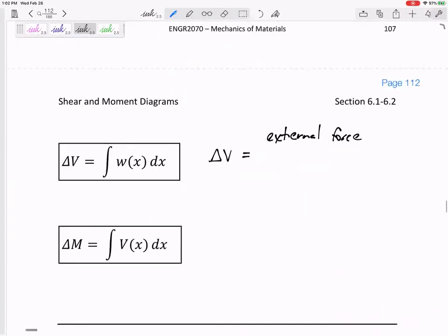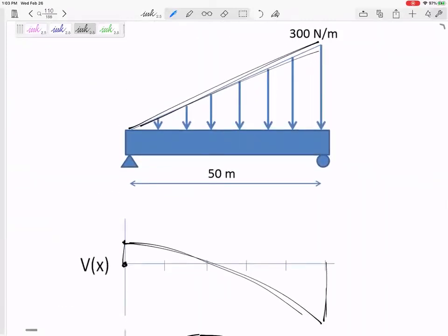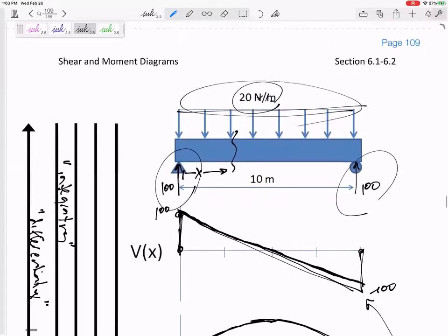Also, distributed loads, they don't push my shear diagram up and down immediately, right? It pushes it down over a length. So let's go back, and we're going to have time to walk around. I'm going to get y'all to walk around and look at these. But do you see that distributed loads like this, it pushes it down, not immediately, but it pushes it down. Let's see if we've got, yeah, look at that one. You see how it pushes down my shear diagram.